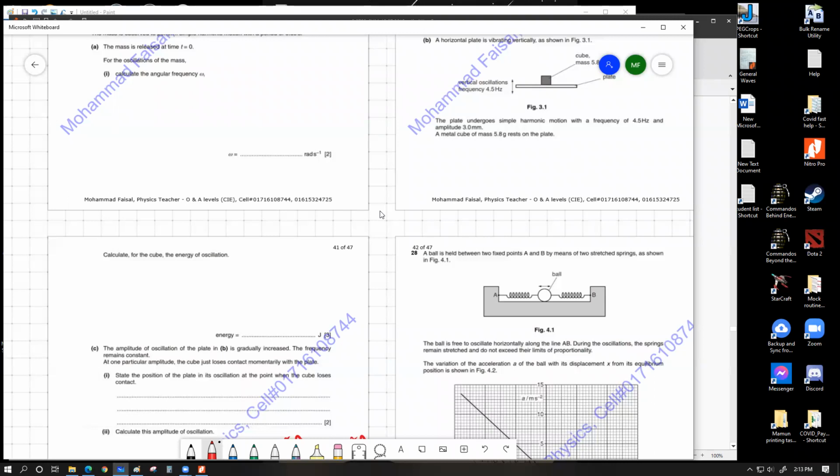When that limit is surpassed, the object is going to start slipping off. We also had one other question: if we layered the whole spin table with clay, the clay particles close to the periphery are going to start to slip off earlier, and clay particles close to the center are going to take more speed to slip off. So this is a similar scenario, that the farther we go out, the more we'll have.